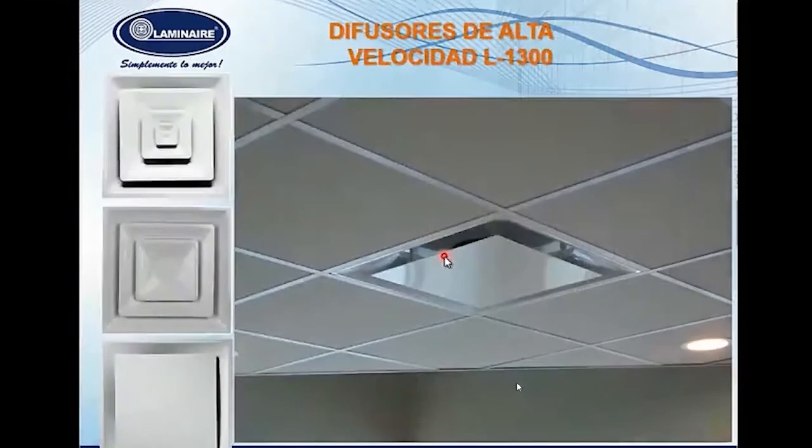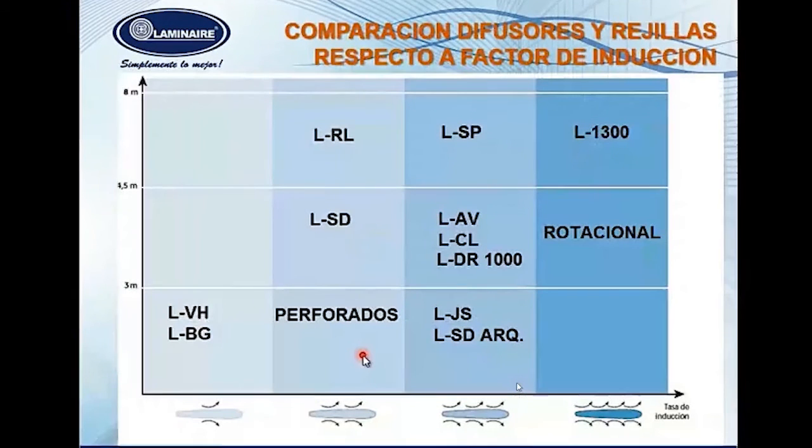So right here we can see the products installed in a modulated ceiling with some standard. Right here we can see a summarized chart of the grills or diffusers depending on the induction rate, checking the ones that have a bigger induction, and this is related with the heights: 3 meters, 4.5, and 8 meters. So we can see which diffuser has a higher induction and what heights they are able to work at.